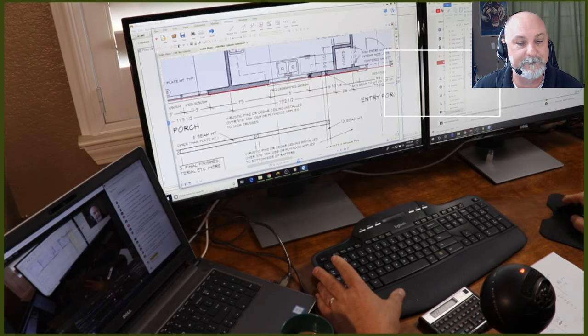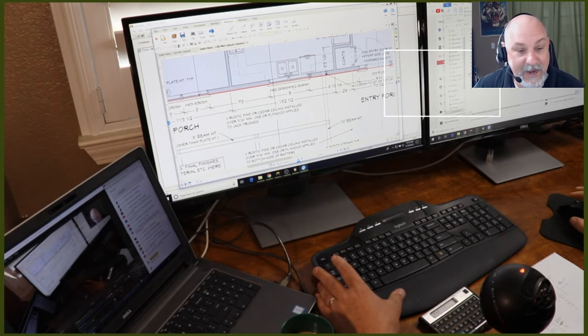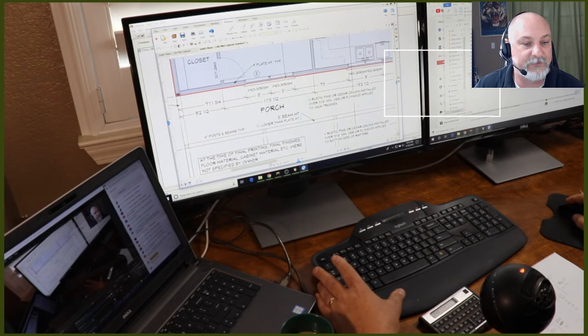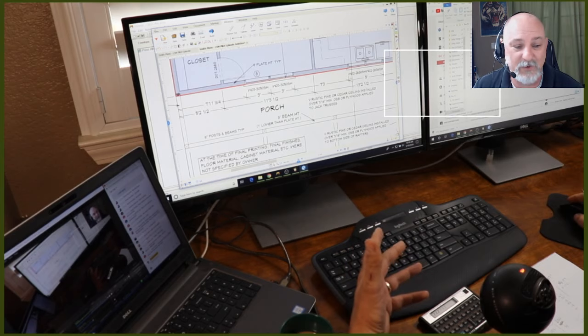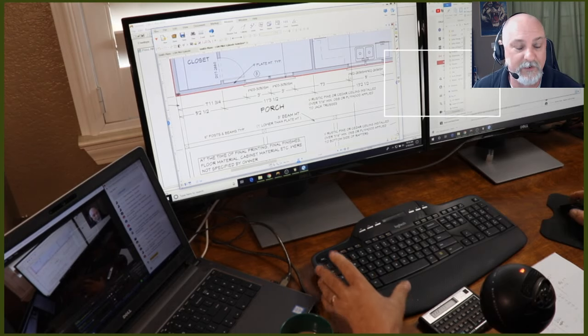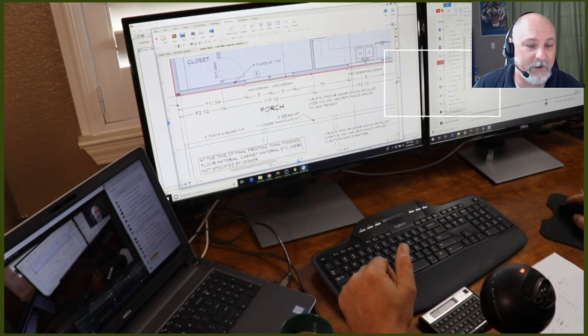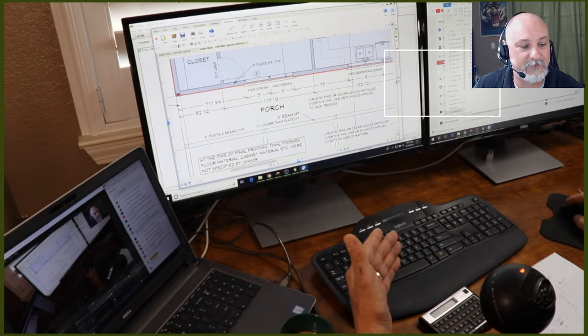So, all right, I've got another pair of 2636 windows. I'm going to call it a 5036, which is 17 and a half square feet. And then our next window here on the front is a pair of 3050s, so that's a 6050. I'm going to call it 30 square feet. Now, if all of those windows were the same window type on the front, I could lump them all into one window area. That's perfectly legitimate. Later on, I may want to take advantage of the shading, and in that case, I want to enter windows separately.